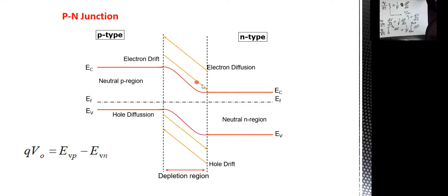It's a sliding space. So whenever you have an electron here, it will go typically in this direction till this area, this sliding area, is empty of electrons. Similarly, whenever you have a hole here, this hole will automatically slide upward and go here, because again, the energy of holes decreases downwards. So holes are going to slide in this direction till it reaches this point. Accordingly, at thermodynamic equilibrium, there is no probability to find carriers in this area.